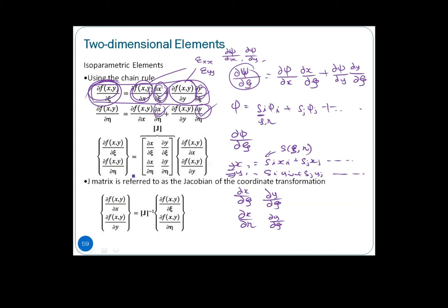If I have this derivative from the position functions, then at the same time we have these two derivatives from these parameter functions, the displacement field functions. Then we can determine our derivative with respect to x and y in this case. So you rearrange everything in terms of matrix form, as you have seen here. This itself we call the J matrix or Jacobian matrix. Pre-multiplication by J inverse makes this thing become I, so we can determine these particular parts.